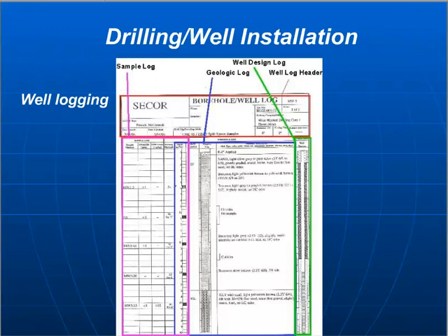And a lot of times I found, after a well is installed and maybe the chapter wasn't there to oversee the entire installation, and there's a problem. There's a lot of sediment in the well. They're just not getting the flow rates that they expected to get. And to kind of troubleshoot the different options, having a bore log like this is just essential for trying to understand what the situation might be and how to fix that, to kind of start narrowing down the options.